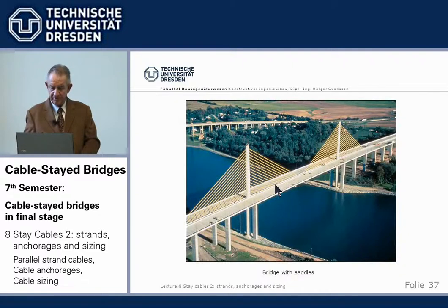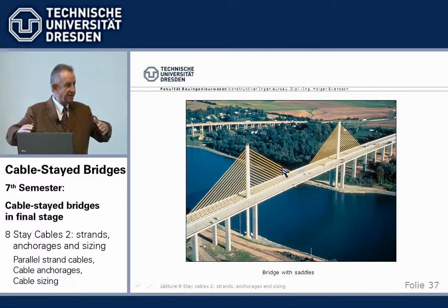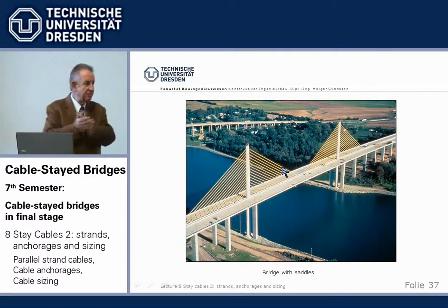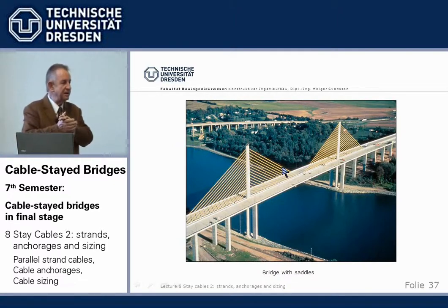If we have a truck load standing here, then the force is transferred by the cable up here, and a large part of it goes up then to the backstay cable into here. Which means this part of the cable is under live load stress, and this basically has no live load stress, roughly speaking. Okay, so we have a difference between left and right in the cable, up to 30-40% of the cable capacity. And the cable must not slip through, must not slide.